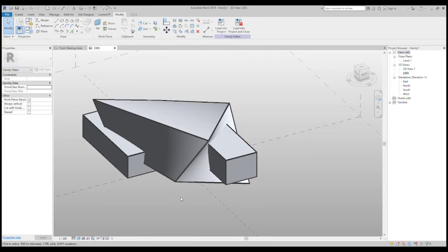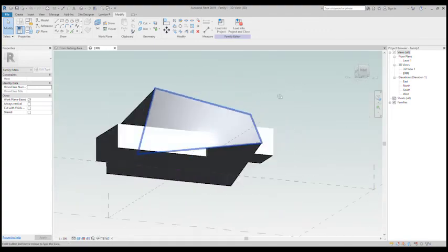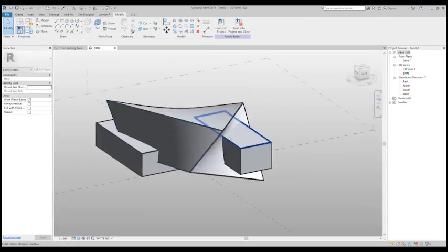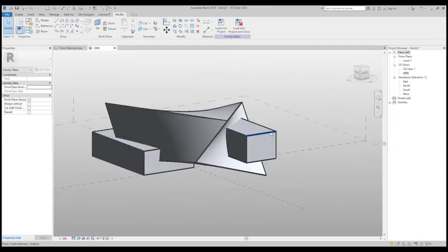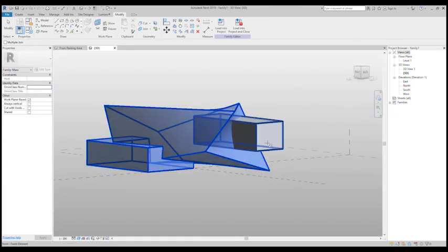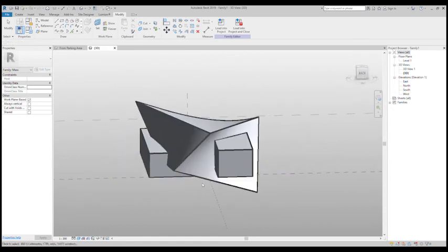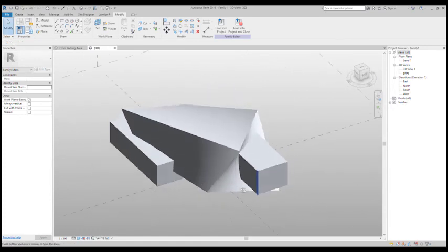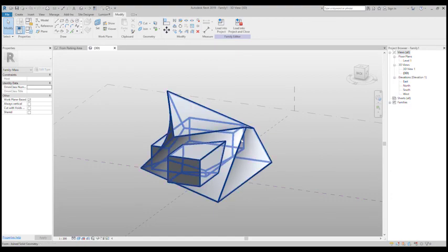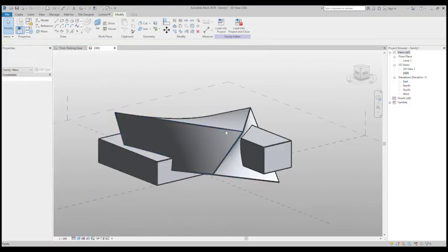And remember, when you want to have mass floors, guys, today we're going to go through just adding walls and floors and roofs and columns and internal walls to this building rather quickly, and then move over to making things look better. So in order for us to do that, we always have to make sure that our separate volumes are always joined. Okay, and if I click on join under modify, I can now join my volumes. So now I've joined those two, and then those two with that one, and now you can see once we hover over, it's a single volume, and we press tab, it's a single volume.